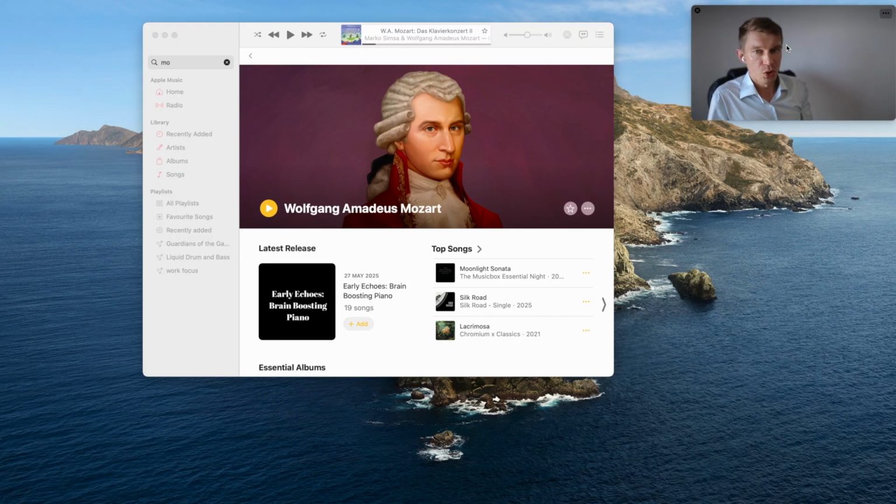So we've trained a model that consumes raw accelerometer and gyroscope data, 6 axes altogether. We've collected this data previously and labeled it into 6 different hand gestures: swipe right, swipe left, double knock, double thumb tap, and then clockwise and counterclockwise rotation. And then we've configured these classes to control audio and video playback features on a computer, Windows or a Mac. So we've introduced business logic into the machine learning model outputs. So let's see how this works.